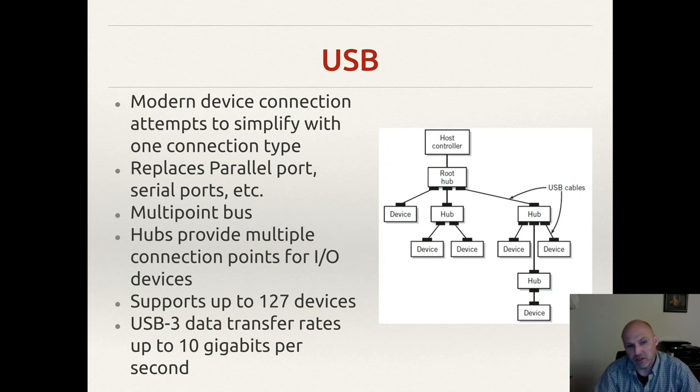Another advantage of USB is it provided power over the bus. So in addition to having a serial bus for data transmission, it also had a 5-volt power line there as well. Now it can only provide 500 milliamps, but it does provide power. So for example, this is how we actually power our Arduinos when we're plugging them in on our USB line. This gave a huge advantage to all kinds of new peripherals that might want to exist in the world, but didn't want to have to figure out how to power themselves.